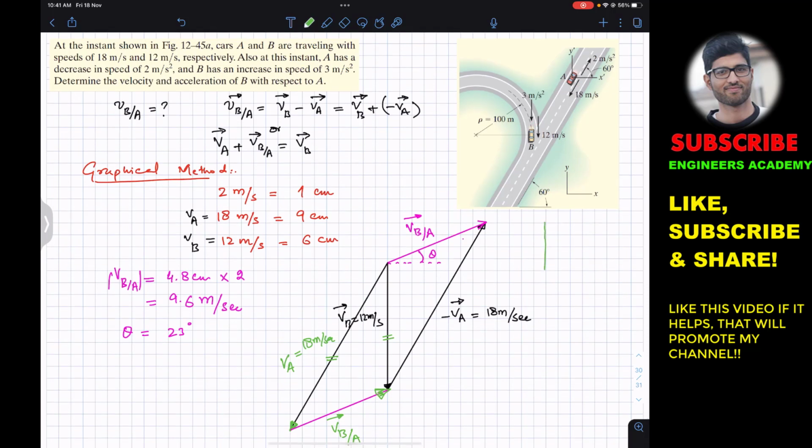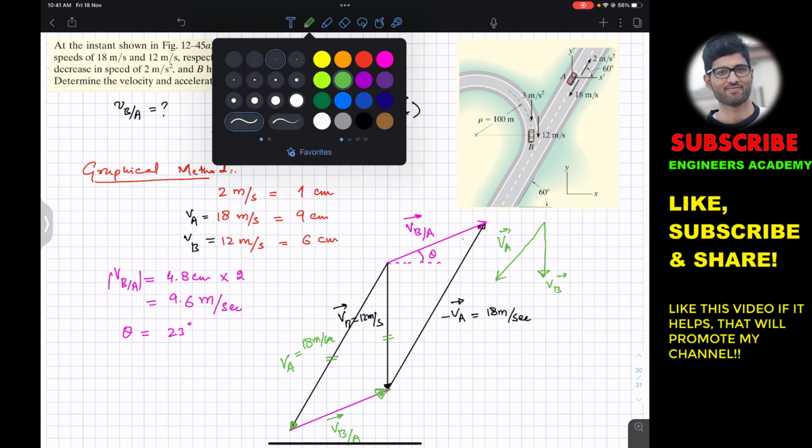So this is VB vector, and this will be our VA vector, and we just need to join their tails, right? So VA, VB, and then we want to find the velocity of B relative to A. So we need to draw a vector starting from A, and that will end at B. So we will have the resultant like this. This will be the resultant.